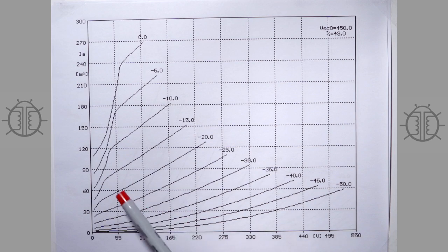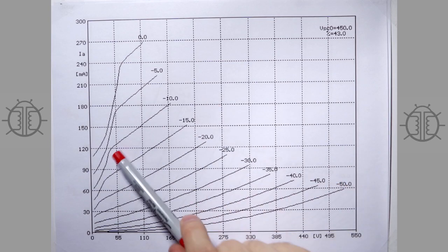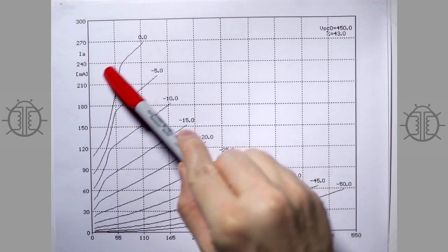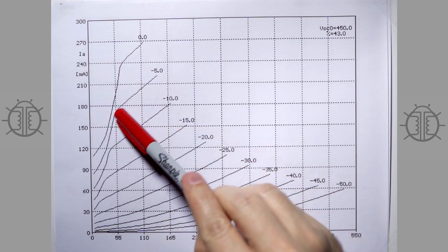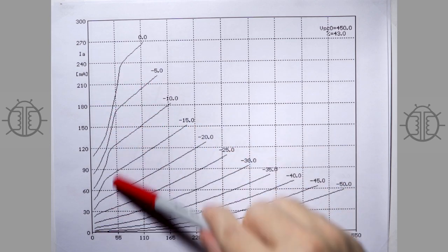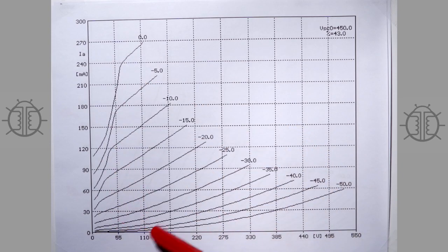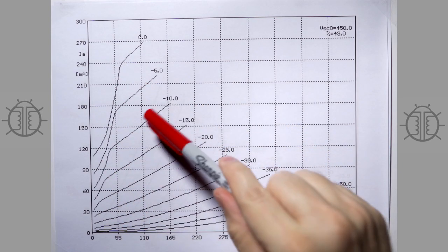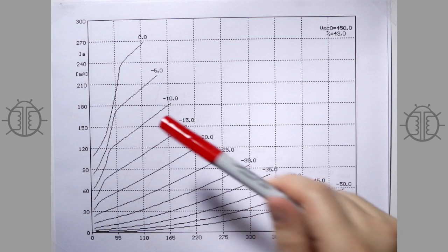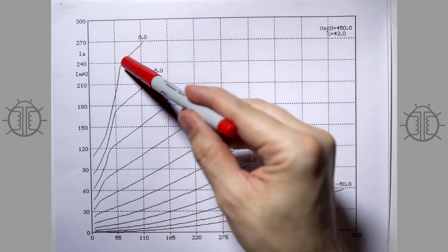So it still gives you some of the voltage sourcey, low output impedance characteristics of the triode stage, but also, if you'll notice, gives you access to this whole area that we never had access to before. So we can swing lower in voltage and higher in current than we could previously. Previously, we were stuck right in here. And so you can see why ultralinear is making more power now.